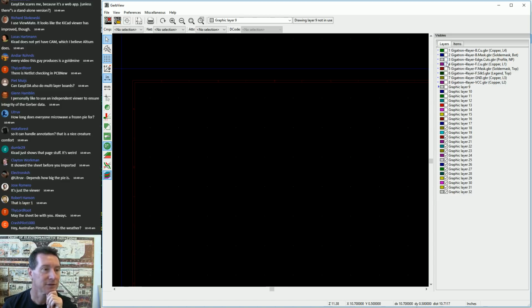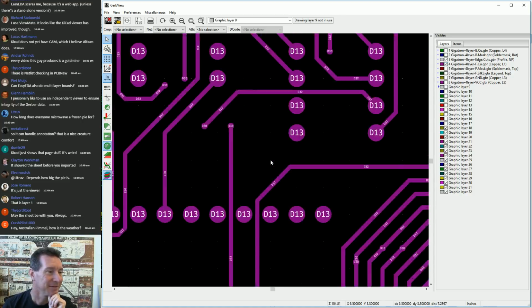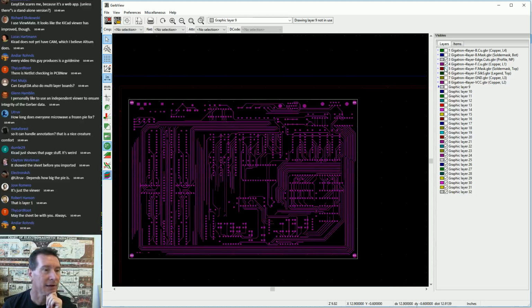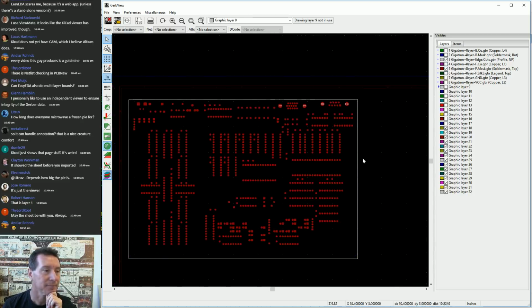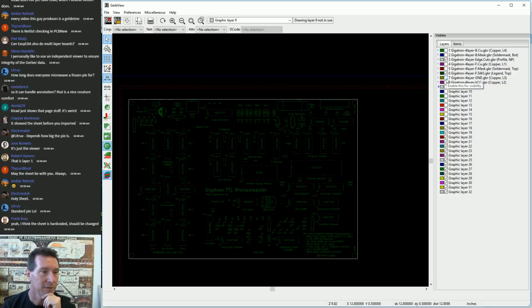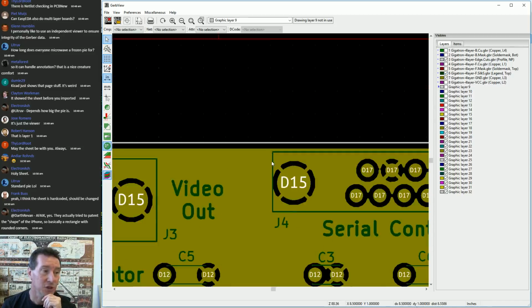There's our edge cuts. I find that name fascinating. So yeah, the Gerbers look good. They're all lined up. We didn't goof anything, because you can goof it up with absolute origin versus another reference. So there you go. And we want to check for our pullback.